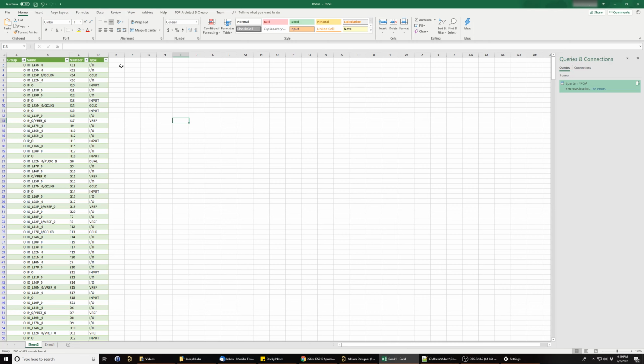Using Excel makes it easier to manipulate the data and format it in a way that Altium will be able to batch add them correctly from a feature called the Symbol Wizard. In this example, I've already formatted the pin data into a tab delimited Excel file with a number for electrical group, the name of the pin number or designator, and the pin type.